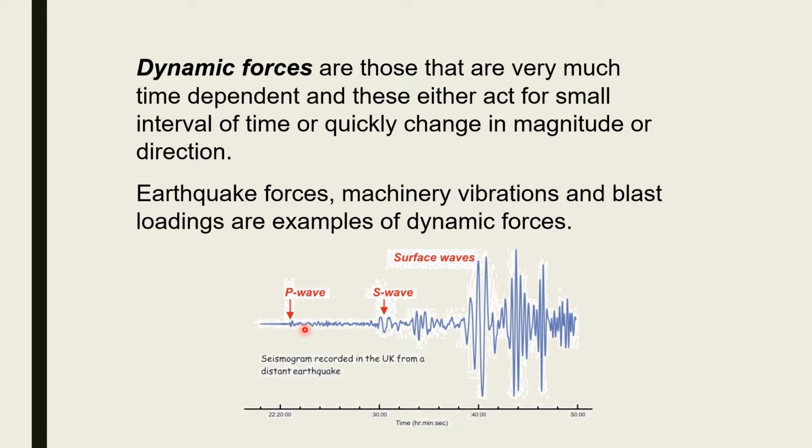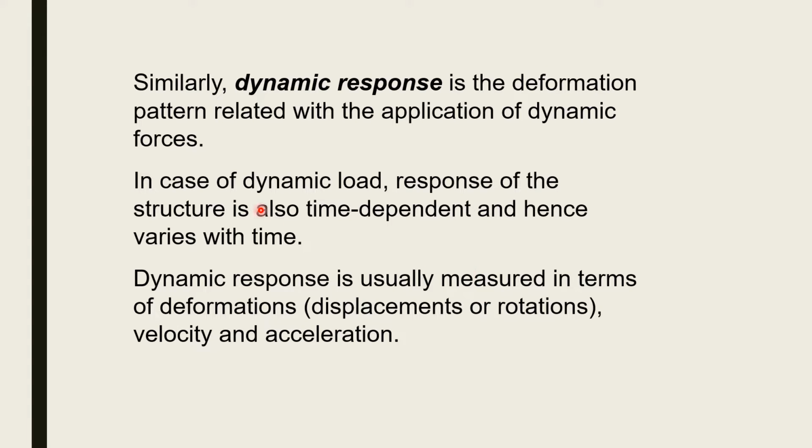When the earthquake loading magnitude is small, the structural response will also be small. As the time is increasing, the magnitude is increasing, then the structural response will also be amplified and have higher values of deformations. So in case of dynamic load, the response of the structure is also time dependent and hence varies with time, meaning it will have different magnitudes of deformation.